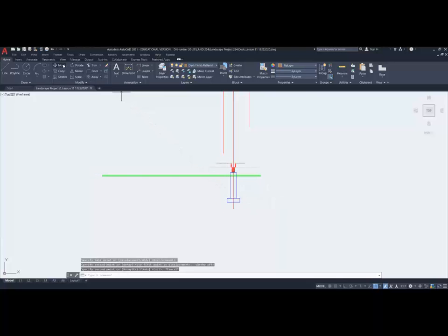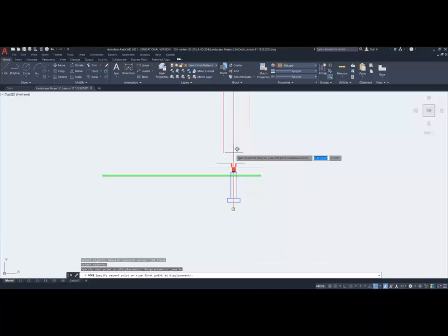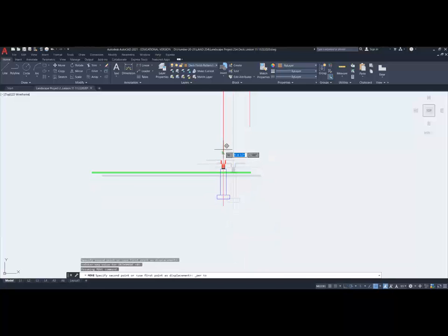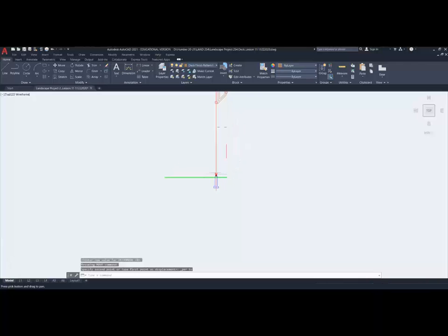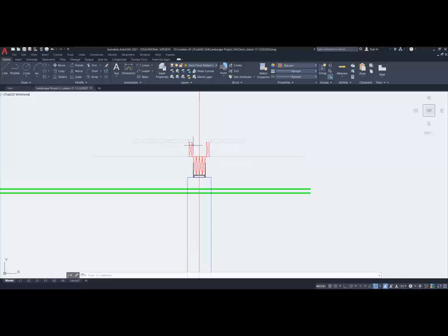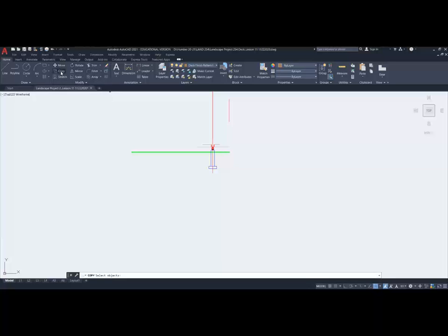Now I'm going to move it in place. So move this from where? Well, anywhere along this red line and hit anywhere along this, it's like perpendicular, that line. So that's where my beam is. Here's my item where I have my opening, and here are some joists. I'm leaving that just for references so I can copy and paste and move it around later on. And now I'm ready to create my second beam.